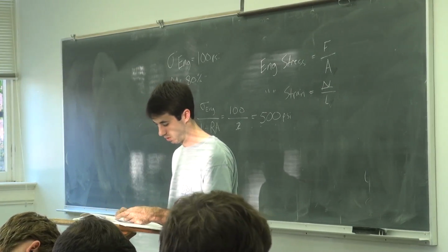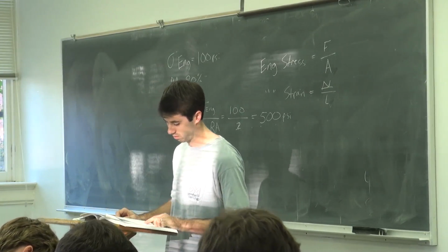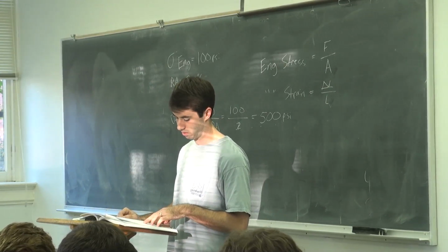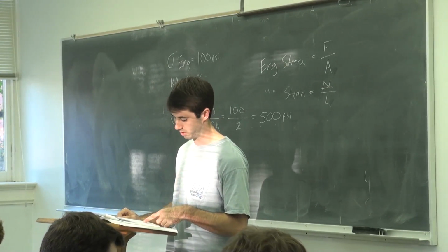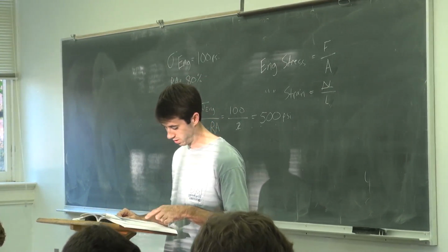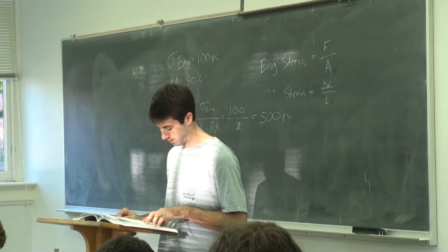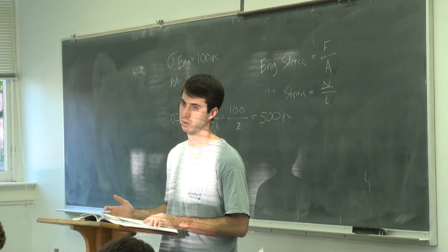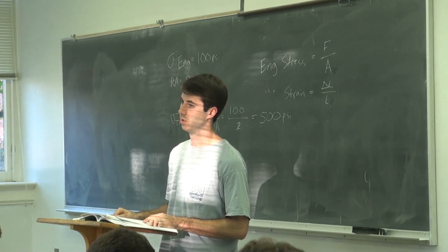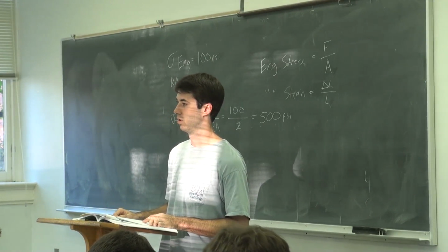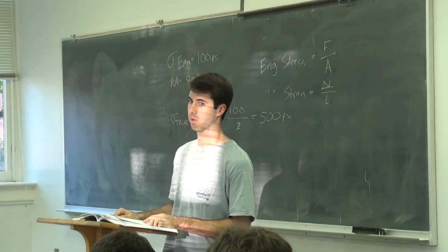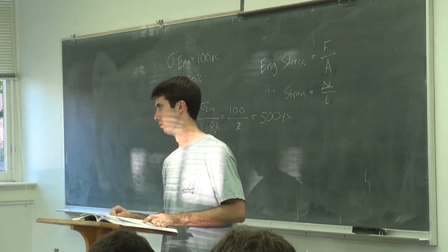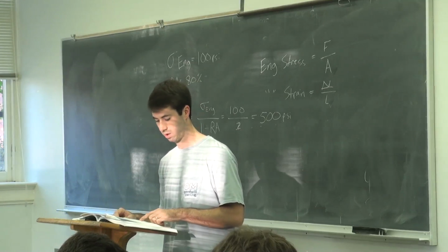Then at the bottom, we got the structural number determination equation, where it's an iterative type equation, but you put in your predicted traffic, which would be your W18, the number of ESALs, the ZR, S0, that is, anybody know what that gives you? It's your reliability. So that wasn't in the original 72 AASHTO guide, it's in there now.